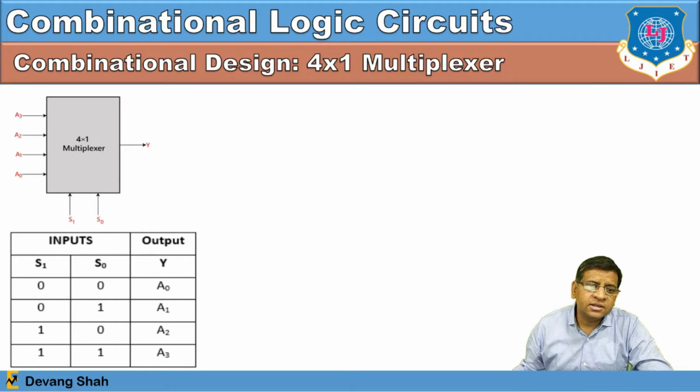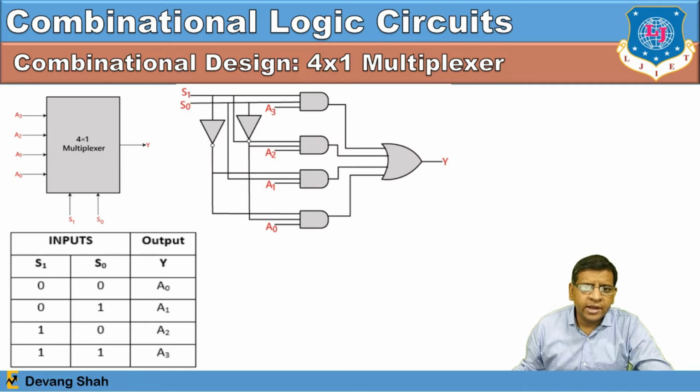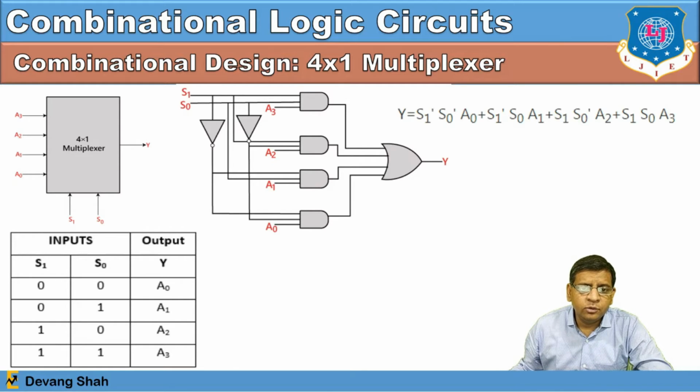That is based on a selection line of 00, 01, 10 and 11. From that you can have a kind of design of multiplexer where y is directly connected with A0. From that you'll have a complete function of y. See here, the y is nothing but A0, which is going to be selected when S0 and S1 are both 0 0. So when S0 and S1 are both 0 0, then A0 would be selected.